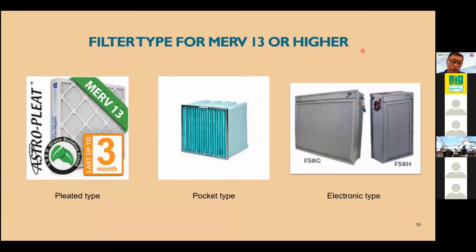So talking about filters, in the current building design, ACMV, of course the air handling unit, you will have a built-in fan. But you have to check first. The fan is mostly not catered for a higher static filtration system, higher static filter.